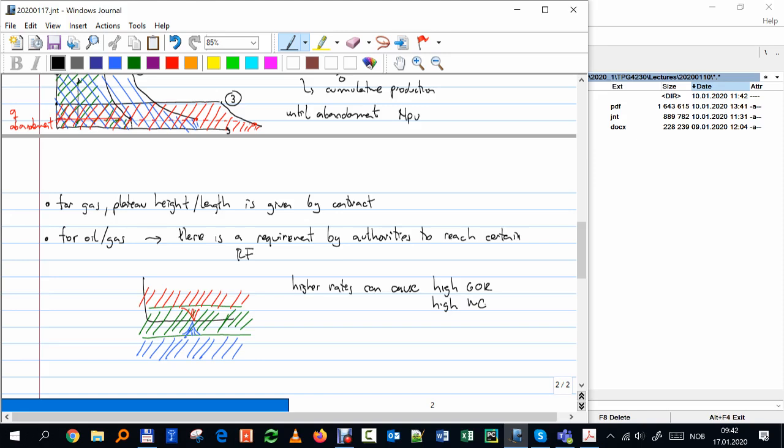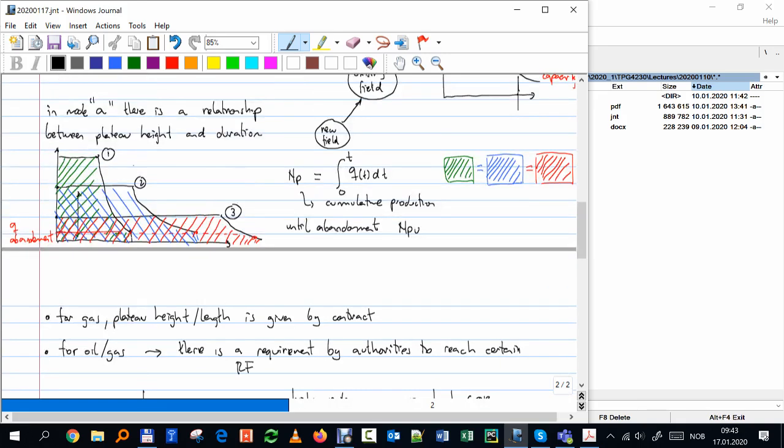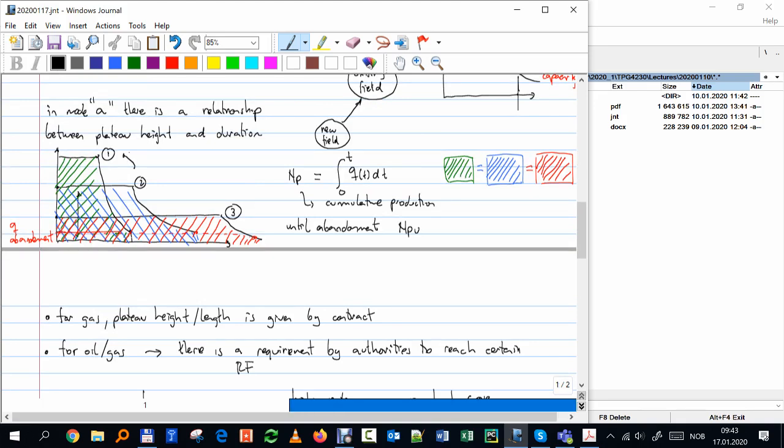which is not good for recovery. If you have channeling between the gas layer and the oil layer, then you are going to leave some oil behind, which is not desirable. You can also cause sand production, and in very extreme cases, a collapse of the near wellbore formation. So if that's a constraint, you don't want that, and it can affect your recovery factor. Of course, you want to get more and more. You want to maybe produce at 1, close to 1, without adding more wells, because that's going to increase the cost.